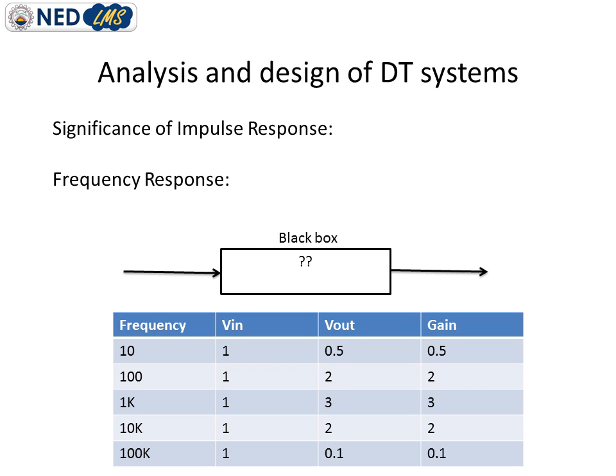By this I mean, for example, at the input side I first set my input voltage as 1 volt, as represented in this table also, and with the help of a function generator I set the frequency of this input voltage signal as 10 Hertz.